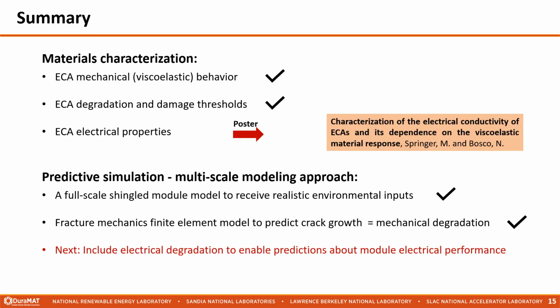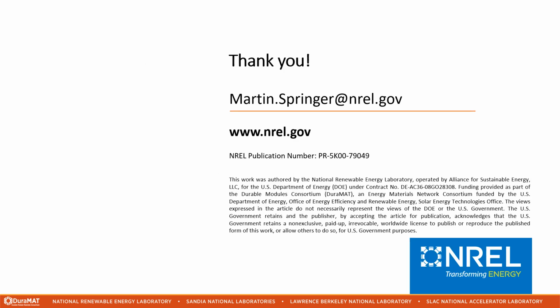In summary, we have finished our efforts for the mechanical and fracture characterization of ECAs and are continuing to quantify the electrical properties. Further, we've developed a predictive simulation capability using a multi-scale modeling approach, allowing us to conduct a fracture mechanics assessment of the ECA joints. In the next step, we are going to include electrical properties into our simulations to allow for the prediction of the module electrical performance.